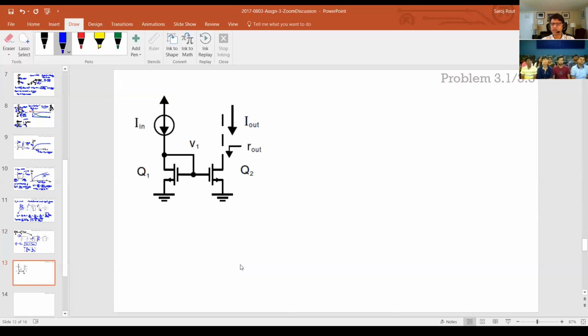They can only mirror the current you give them, right? So that pristine source is a current generator. And that's a little involved. What you need is what's called a band gap. And we'll actually have a project related to the band gap. When we come to that, we'll realize. Essentially, the bottom line of the band gap is we use a BJT, a difference of 2 BJT voltages across a resistor to generate that current.